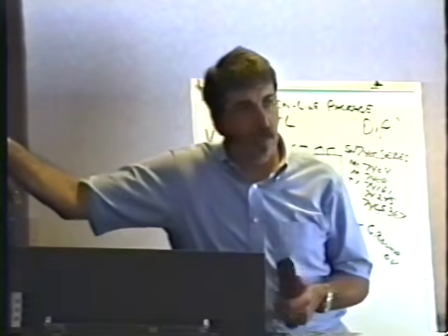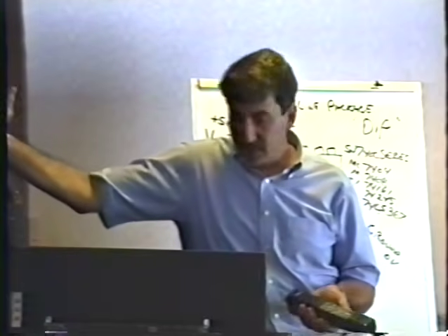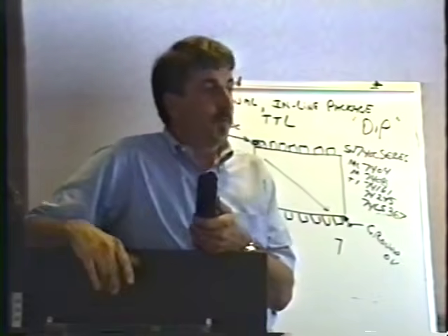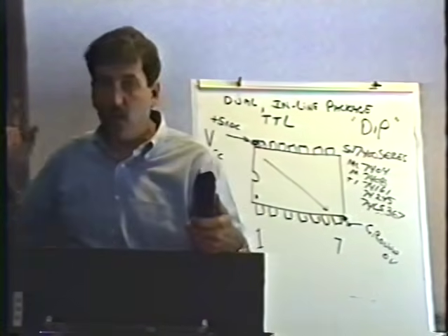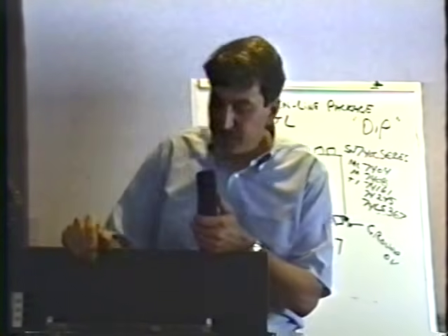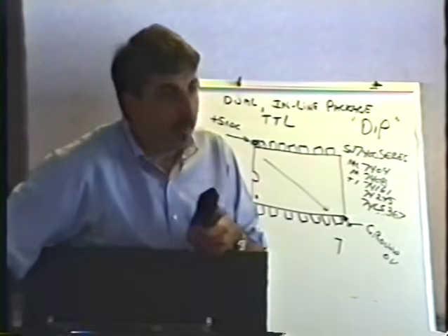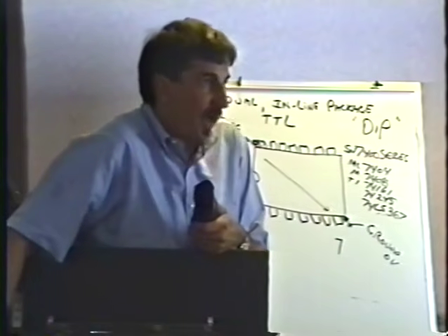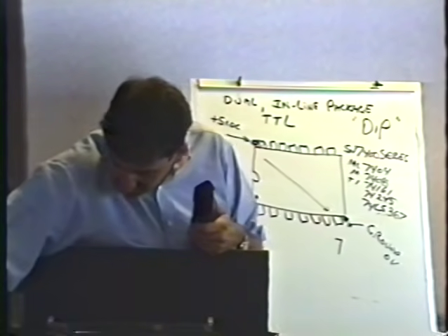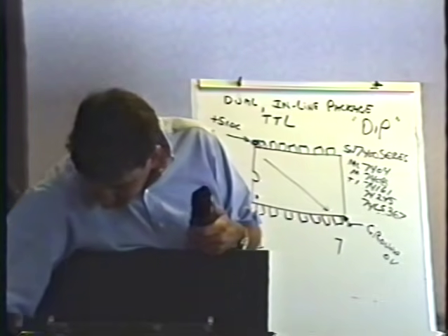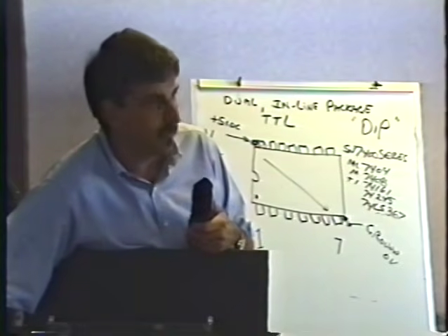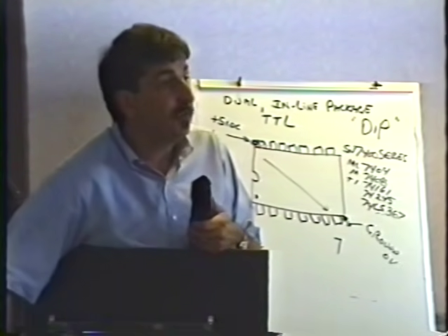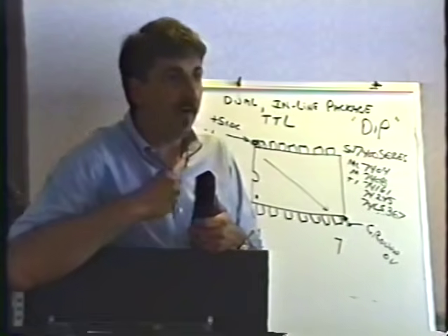This was really cool. This is a typical kind of thing that comes into the shop. First of all, the power cord was bad, so I cheesed a little temporary power cord on there, and it's working. So then we got the marquee up. No coin, the screen was blank. I coined it up, no game sounds whatsoever. We go over here to the connector, 3.7 volts. Not enough, obviously. With the meter connected here on the connector, I adjusted up the power supply. I don't know whether someone was messing with it or what, but it was way down too low. Cranked it up to 5.1 volts. Fired right up. Came up.